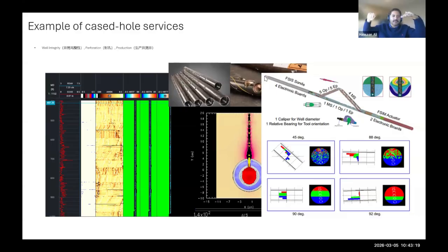So what you do in that case is you either jar the tool, so you use mechanical intervention to push it, or you use a wireline tractor, which is, think of it like a remote control car. You will use that wireline tractor. It is also part of the tubing, the sensor array. It uses wheels to move that tool string further into the wellbore.